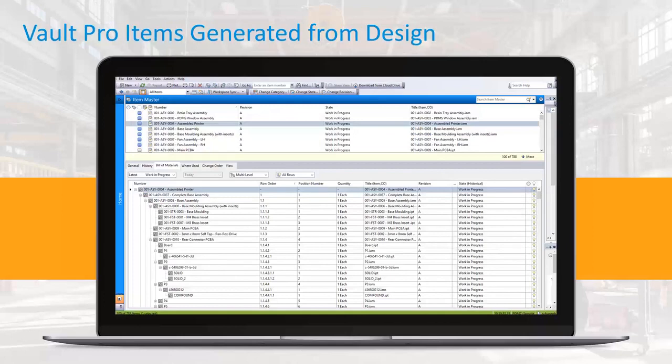Vault has the ability to take that model and mine out, extract all that information, and we build what is known as an item. That is what we just talked about. And it understands all the nested substructures. It's an assembly inside an assembly, inside an assembly, inside an assembly. Maybe it has library components, or in some cases you will notice that there is a PC board on there. We can read information from AutoCAD Electrical and put that together inside one complete bill of material.